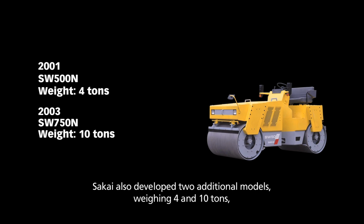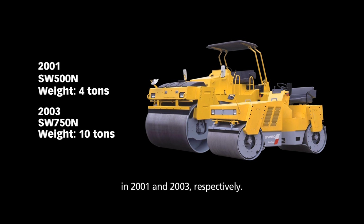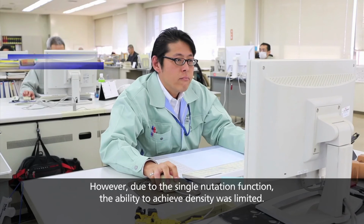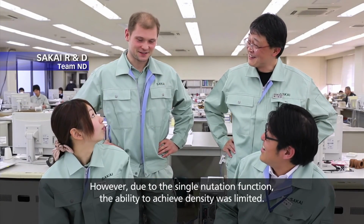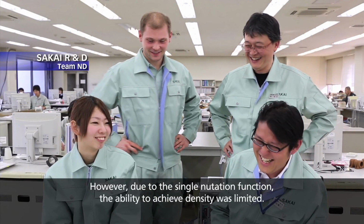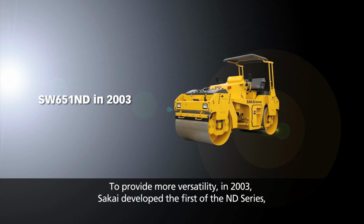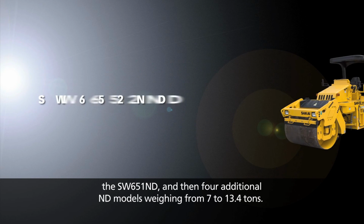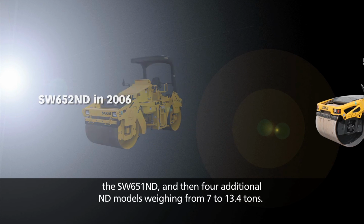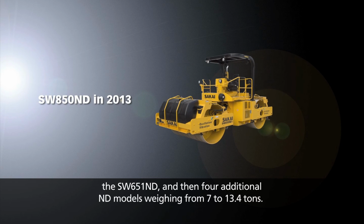SAKAI also developed 2 additional models, weighing 4 and 10 tons in 2001 and 2003 respectively. However, due to the single nutation function, the ability to achieve density was limited. To provide more versatility, in 2003, SAKAI developed the first of the ND series, the SW651ND, and then 4 additional ND models weighing from 7 to 13.4 tons.